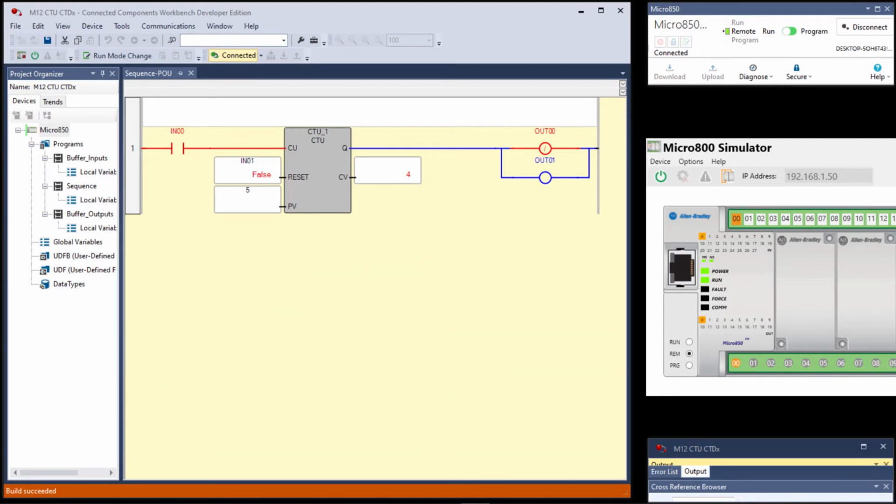There was a question in the manual, did the counter increment again even though you did not operate input 0? Yes. Why? Because the processor went from not running to running, or it went from powered off to running. So the way it executes the logic on the first scan is it sees input 0 is on.